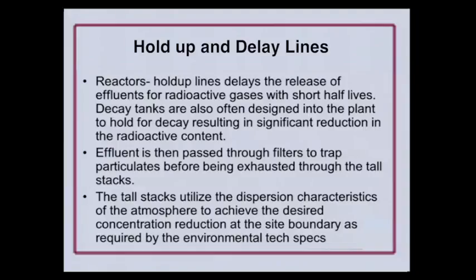It gives you good dispersion and mixture as it goes up through the stack and is discharged out into the air. And you can see down here the concentration is maintained below what is required by the environmental tech specs. Again, everything is geared and designed for maintaining that off-site dose as low as reasonably achievable.